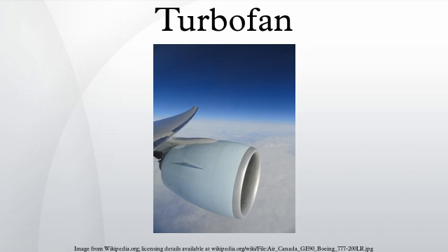U.S. civil engines use much higher HP compressor pressure ratios and tend to be driven by a two-stage HP turbine. Even so, there are usually a few IP axial stages mounted on the LP shaft, behind the fan, to further supercharge the core compression system.